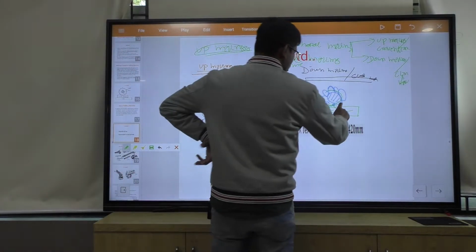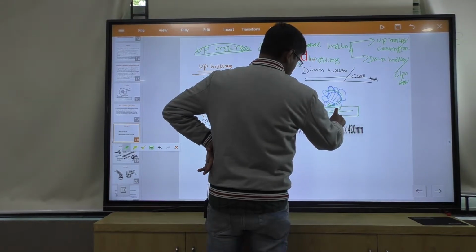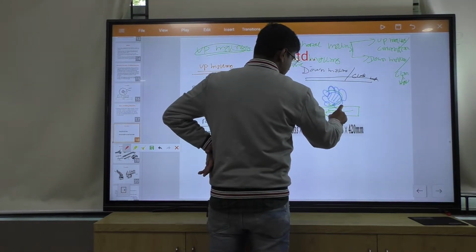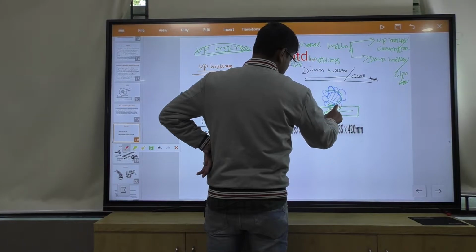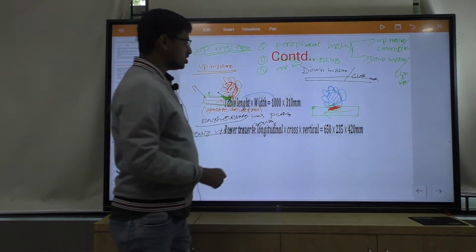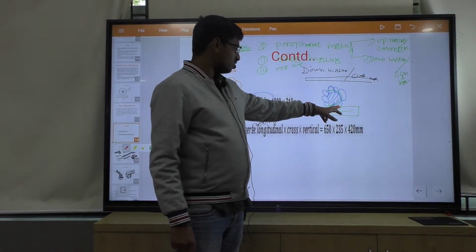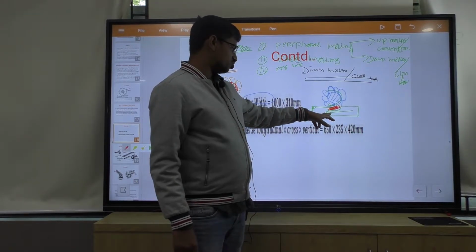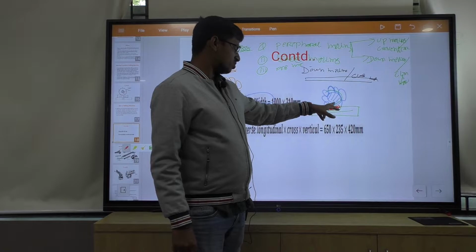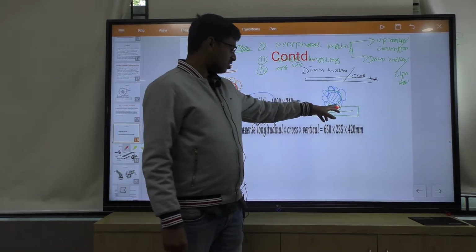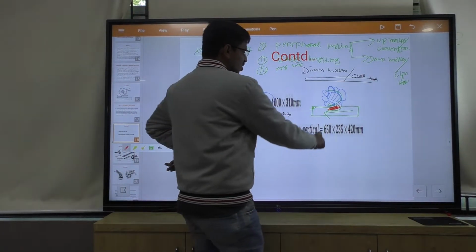But in down milling, the contact of the material between the cutting action and the workpiece goes from high to low. For this reason, as the material is removed from high to low, there is very little force, and very little force for metal removal at the end. This force also acts in a downward direction.